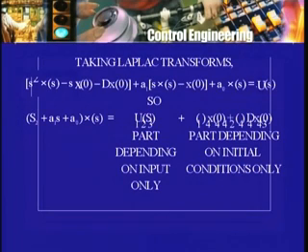So if I take the terms involving only X(s), keep them on the left hand side, and transfer the other terms involving the initial conditions to the right hand side, what will I get? I will get X(s) multiplied by s squared, X(s) multiplied by a1 s, and X(s) multiplied by a0. So I will have s squared plus a1 s plus a0 multiplying X(s) equal to, what do I get on the right hand side? Let me write down U(s) first, plus the x(0), dx(0) terms transferred to the right hand side. So I will write here some expression multiplying x(0) and some other expression multiplying dx(0).